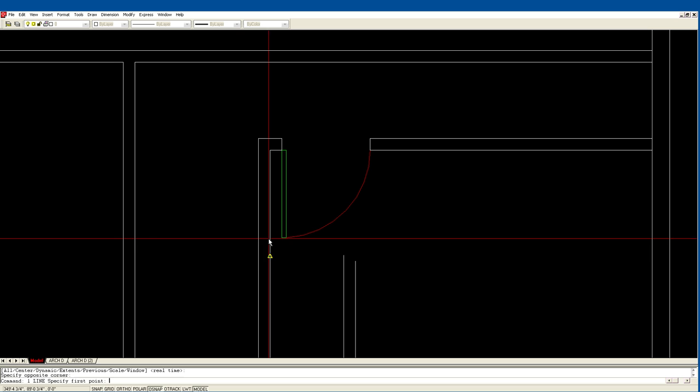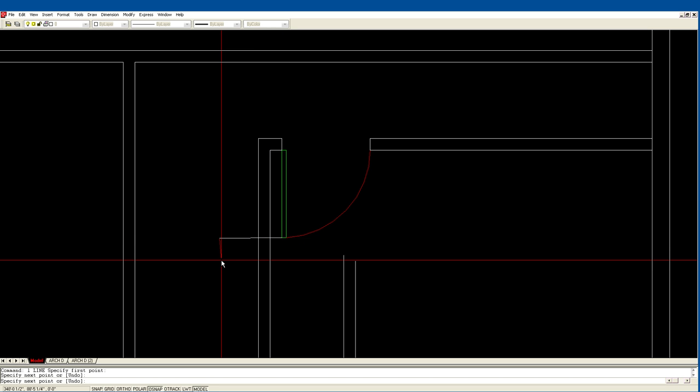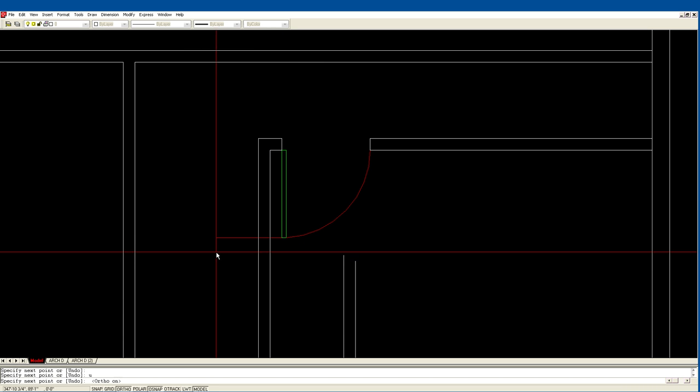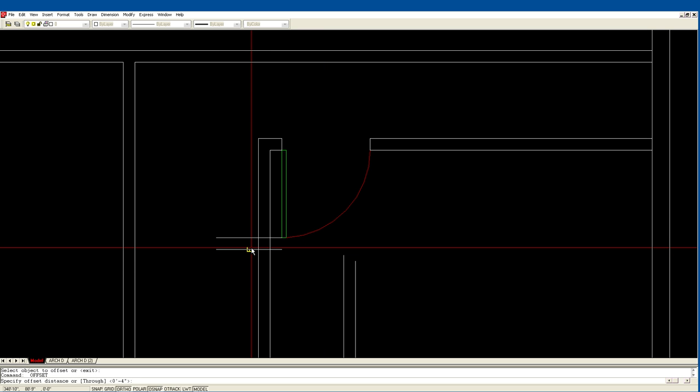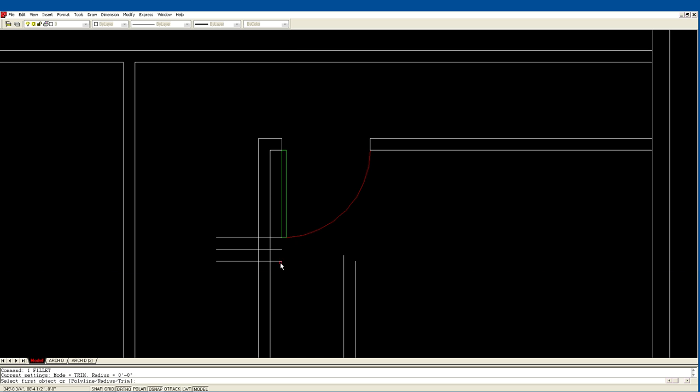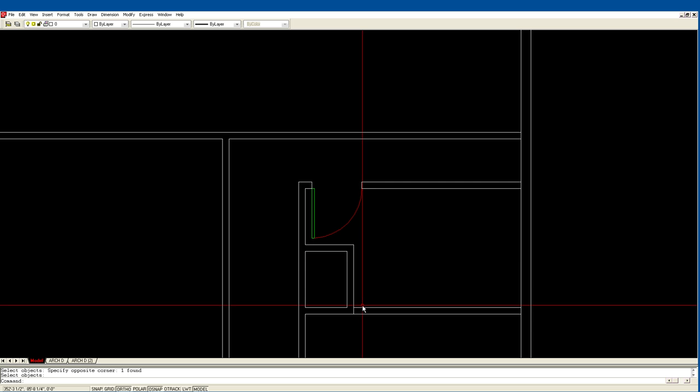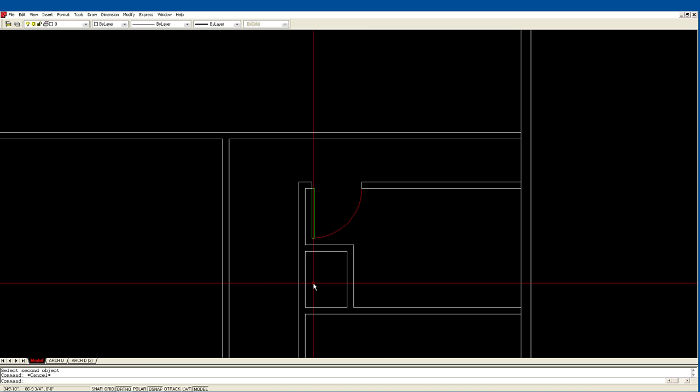So let's just take a line from this door. Undo, turn F8 on, and make it a straight line. Offset 4. And then offset 4 again. Okay, fillet those. Okay, so I kept away from that door. Okay, 4 inches, the magic number. Okay, I've got a closet in here that I can put some little door on. Okay, I'm into this area. Now I have to do,